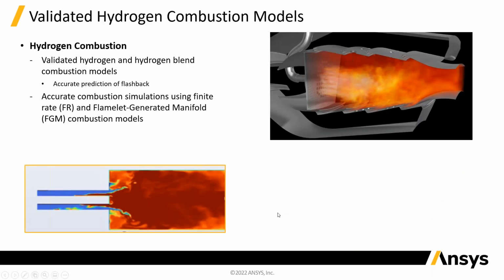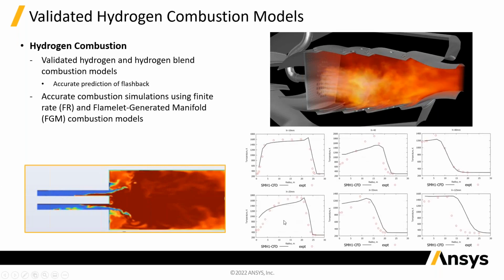Combustion, always a big area. Combining those high quality turbulence models with now flamelet generated manifolds or very good finite rate chemistry. And particular, the focus of this slide is on hydrogen. Lots of validation going on, flashback simulations. So if you're in the combustion area, there's lots going on.